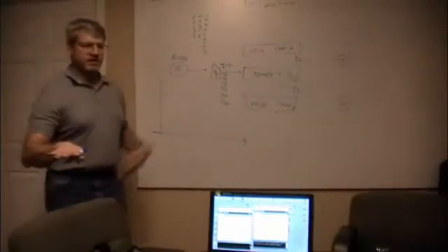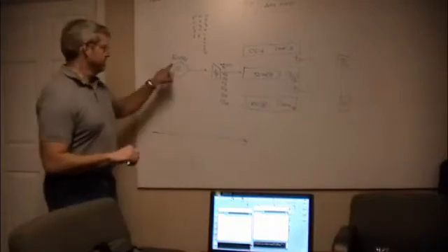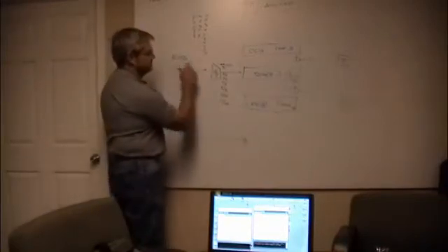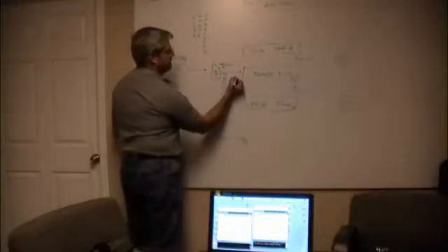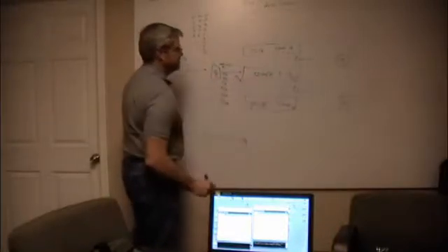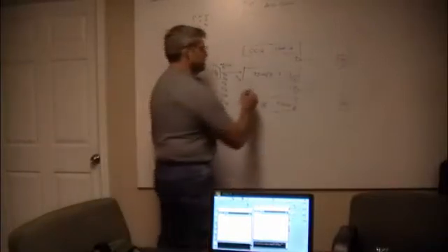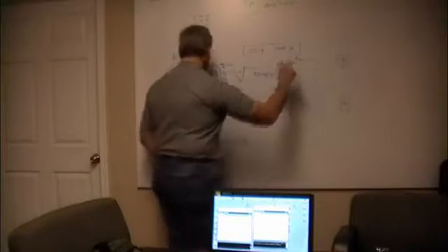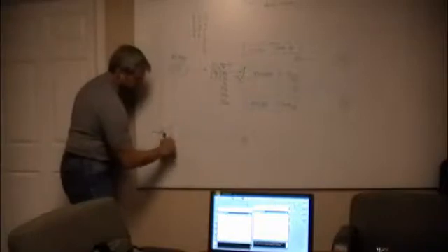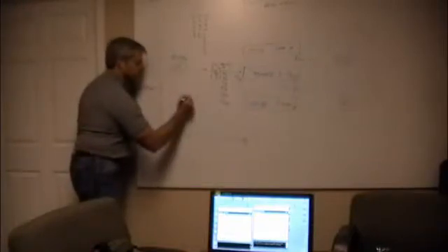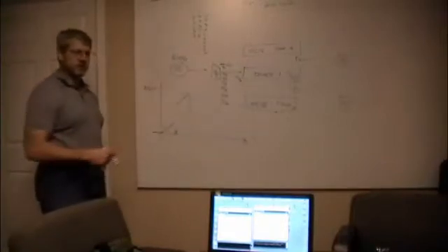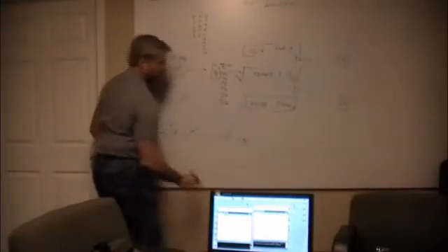The 3 timers are different. They have different numbers. But what happens is you take 16 million, divide by 2, and I've got 8 megahertz going in here. If that's 16-bit, it can count to 65,535. So the time for this guy to count all the way up to 65,535, and then he'll wrap around, right? We talked about the hardware. He'll just count, wrap, count, wrap. He'll do this over and over and over all day long.